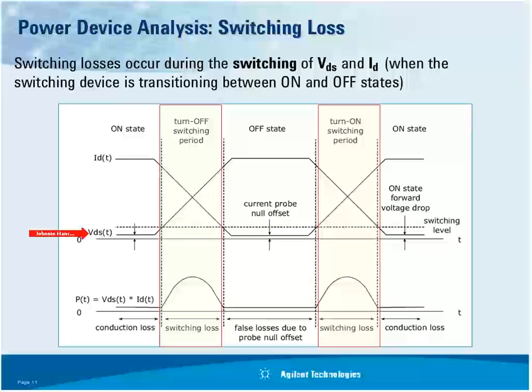And then when the transistor switches to the off state, you go through a phase called the turn off phase. This is when the transistor is actually conducting in its linear range, in which case it is not fully on or fully off, and this is typically where most of your losses occur, power and energy losses. And if you look at the power waveform, which is simply volts times amps, you'll see an impulse during that short period of time.